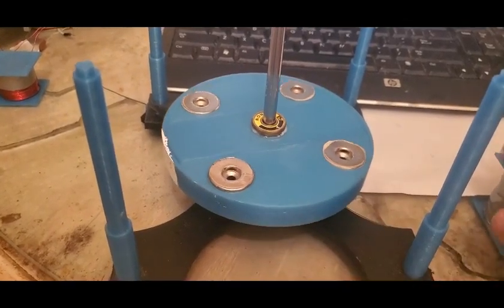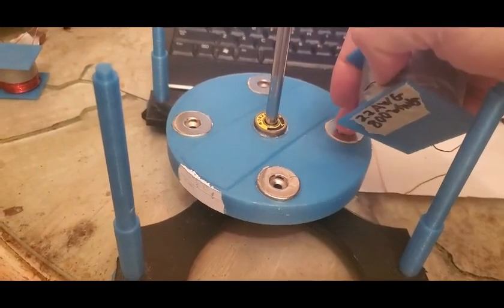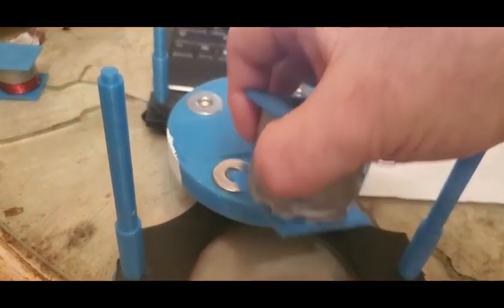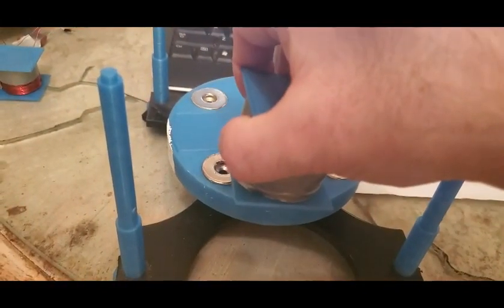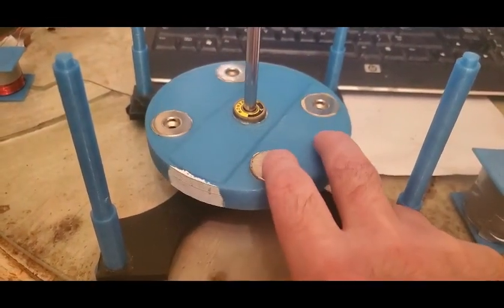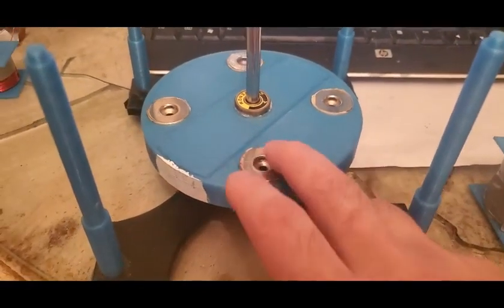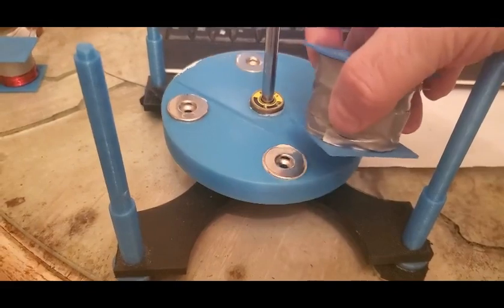Now, one of the nice things when you do that is if you put a coil here, depending on the spacing of the magnets, you'll be pushing this magnet out, and you'll be pulling this one in at the same time. So you get a push-pull, and that gives you a little more torque and a little more efficiency than a monopole setup. But now, first it sees a north-facing magnet, and then it sees a south-facing magnet.